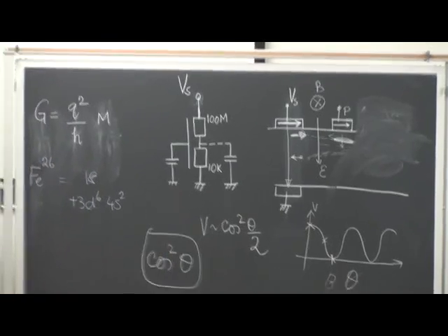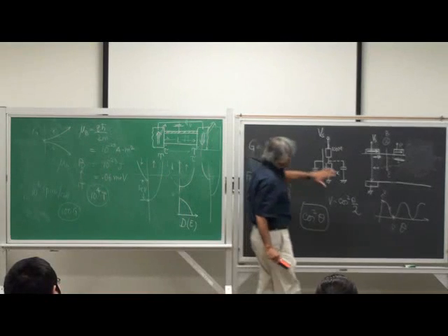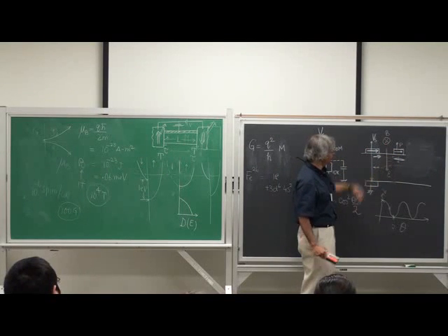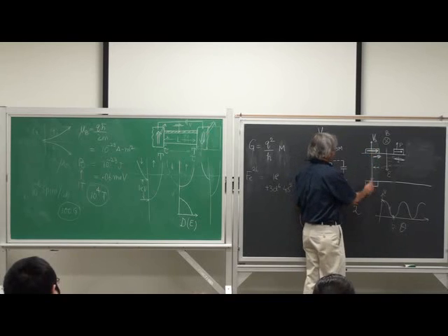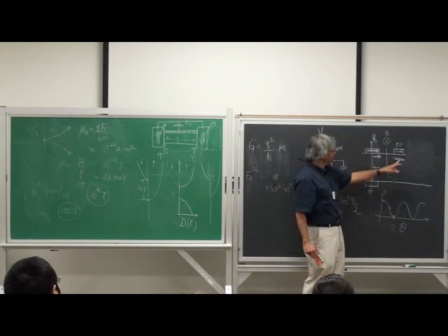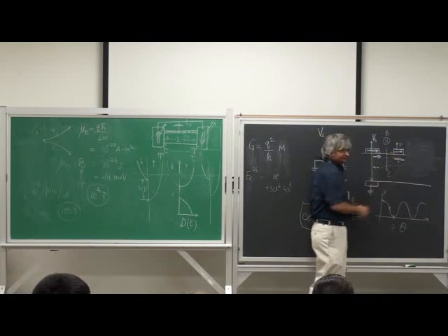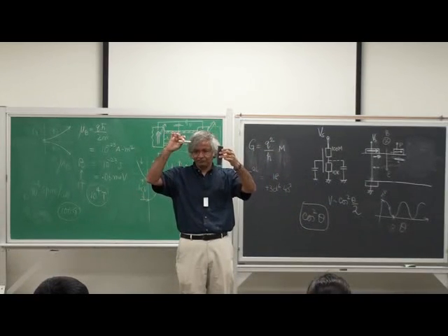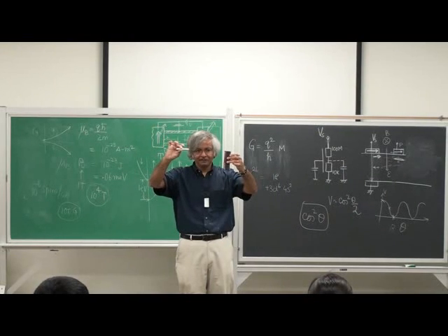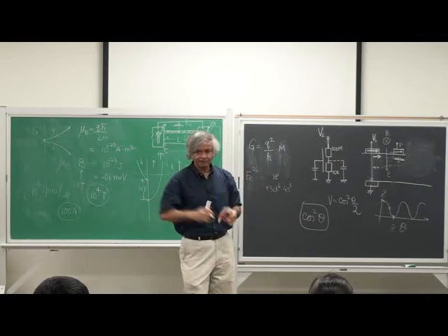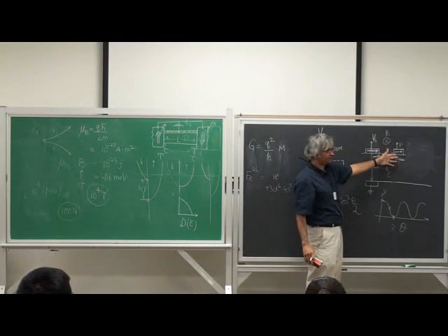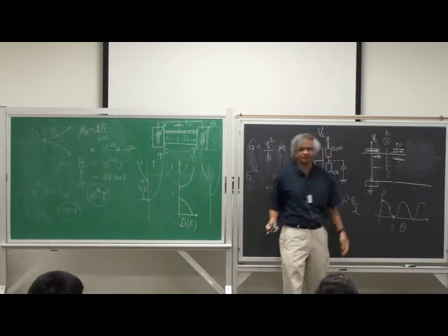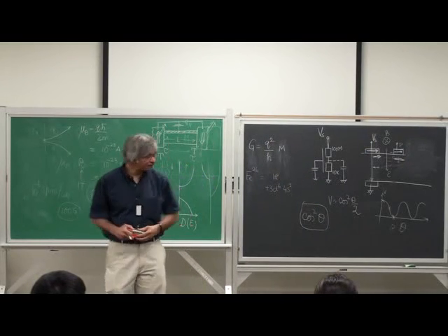But the one point I also want to stress again is that in addition to the spin injection and manipulation, there is this spin torque, which is what people have also shown: you can run a current here, and if you run enough current, that magnet can be made to switch by the spin torque effect. And to me, that sounds amazing. You're running a current here. Here's a magnet sitting by itself, minding its own business, completely out of the current path, and at some point it gets flipped. Why? Because of all these excess spins that pile up. And again, depending on whether you put a magnetic field or not, you can make it flip back again. Some of those experiments people have done, and some they are doing right now. Lots of these interesting things.